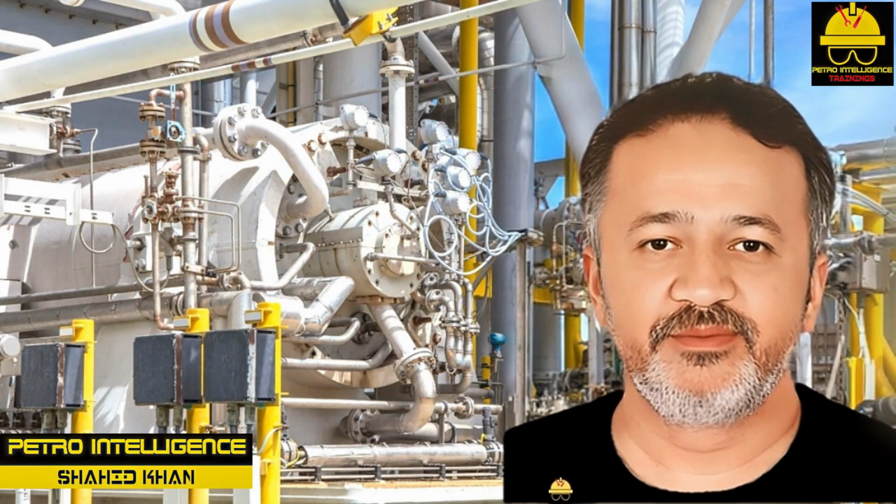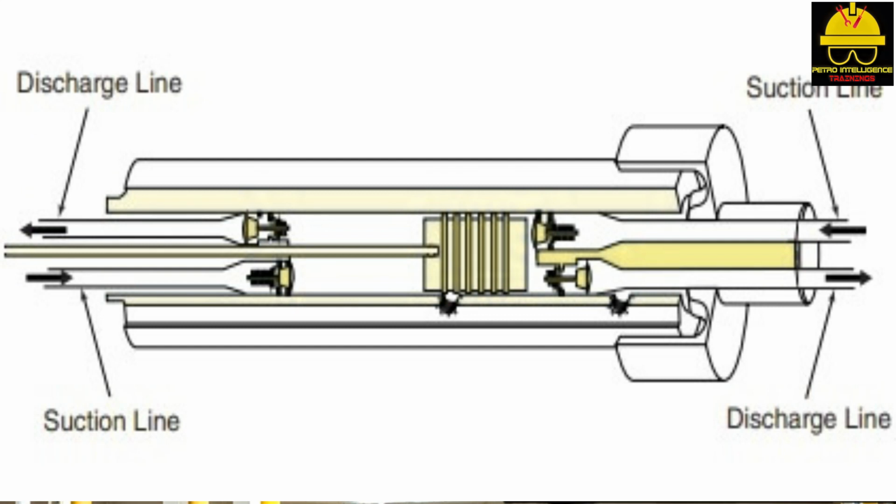Double-acting compressors. Double-acting compressors as shown in picture use a common cylinder and piston to discharge and take in gases on each side of the cylinder. Double-acting compressor cylinders are equipped with 2 spring-loaded intake valves and 2 spring-loaded discharge valves. For example, when the piston moves to the right, the chamber to the left of the piston fills with gas, while the chamber to the right of the piston discharges. The exact opposite occurs on the reverse stroke. This technology doubles the efficiency of the compressor.